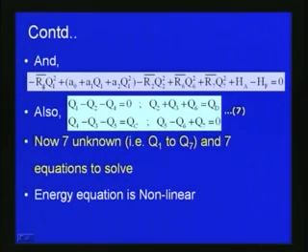for the pseudo loop, it will be minus R1 bar Q1 square plus, corresponding to the pump equation, S0 plus A1 Q1 plus A2 Q1 square, minus R2 bar Q2 square plus R6 bar Q6 square plus R7 bar Q7 square plus HA minus HF is equal to 0.